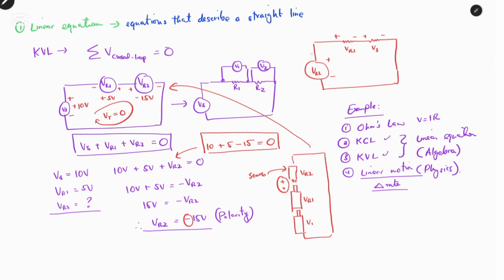So when we have plus and plus connected together, this normally becomes minus, in such a way that we can say that VR2 equals VR1 plus the voltage source. Now from this equation, we can see that this becomes the supply and these two behave as a load.